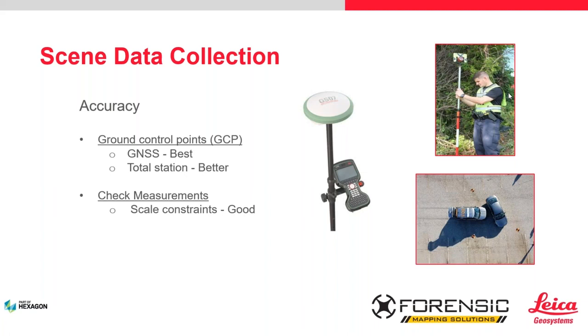So first, a ground control point, I said it's a known point, an anchor, but in the photogrammetry software you need to have targeting or some type of marking in the area. If you look at the bottom right of that slide, it's a little hard to see, but there are 3 targets there that we would then use either our total station or GNSS GPS to capture the location of. So those targets are in your software. We would then upload a data file to Pix4D with our ground control point measurements, or coordinates is a better word. Then we would identify those targets and pick them in the software, and Pix4D would run from there. Honestly, that's really the only manual thing you're going to do in Pix4D: mark your ground control points.